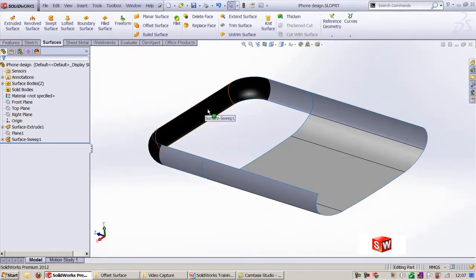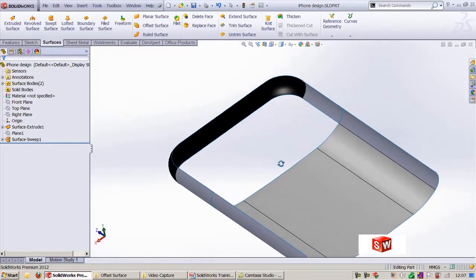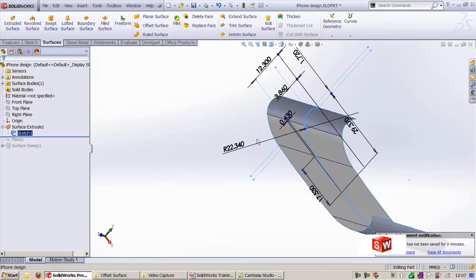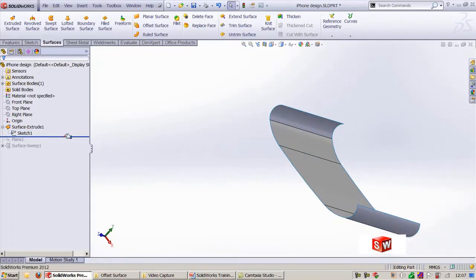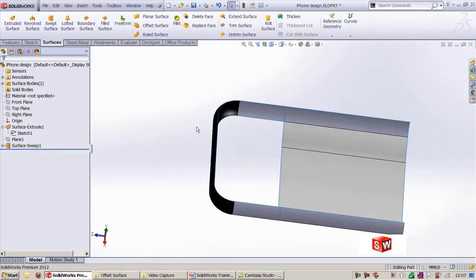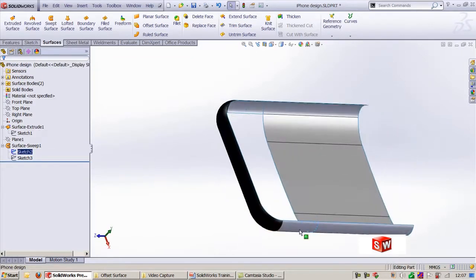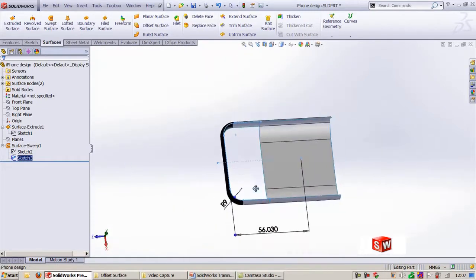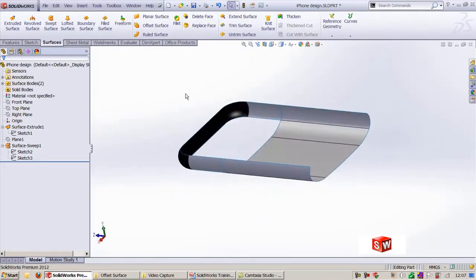This is the iPhone cover. Here this area is open, and we need to fill this open area. Before this, you can understand how this is created. The first initial sketch, we created this base extrude using this sketch. And once I complete this, I created a plane exactly on this point, so that I will use a surface sweep to complete this one. In surface sweep, we used this edge as the section, and a guide curve we had drawn this. Using this we completed this iPhone cover.